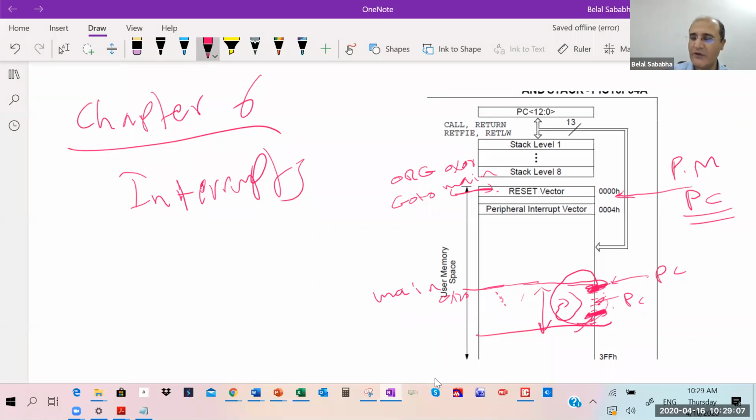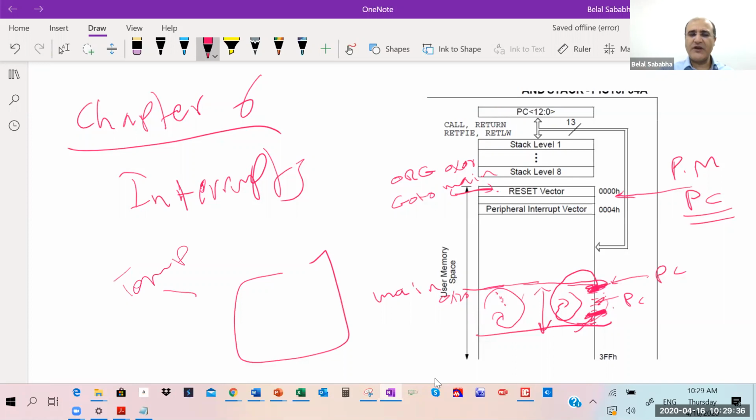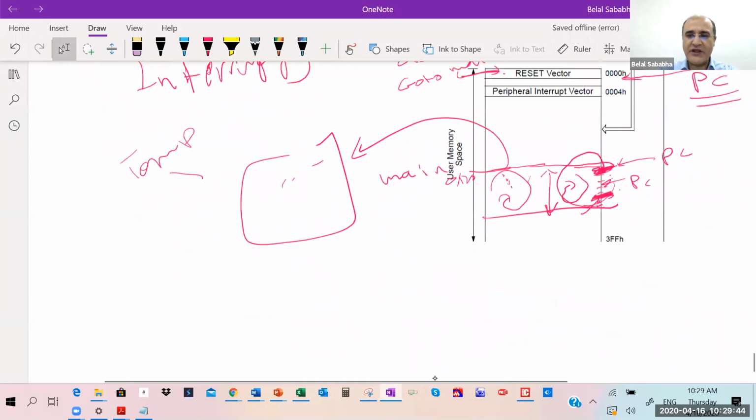When we talk about real-time, even hard real-time systems, you need immediate response. So the idea behind interrupts came from here. Sometimes emergencies happen. So you're executing your code infinitely, but suddenly the CPU heats up or a fire is detected. You need to turn on an alarm. So there is a special hardware that detects if the temperature goes above something, then it will force the program counter to go to this code, which could be actually code written somewhere here.